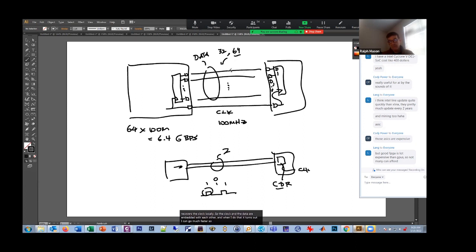See, the problem we had up above here is, these wires aren't perfect. The distance on these wires is different as I route them between chips. So when the clock is going like this, and I'm trying to make this a really small period of time, like less than 10 nanoseconds, the different delays mean that the data arrives at different times. We want the data to arrive before our restricted region. But if some of them come later, I don't catch them right. So that limits the speed.